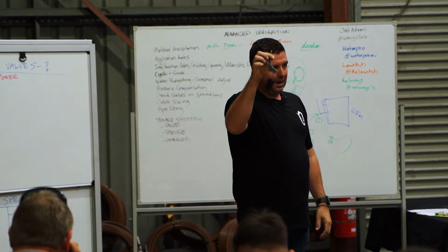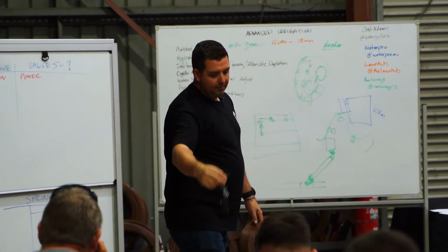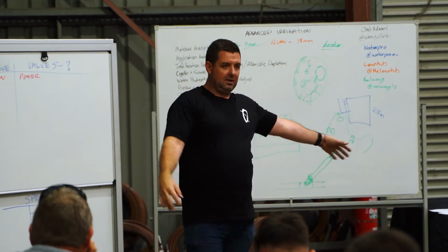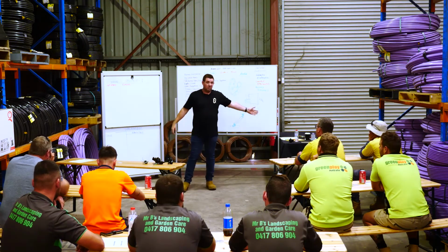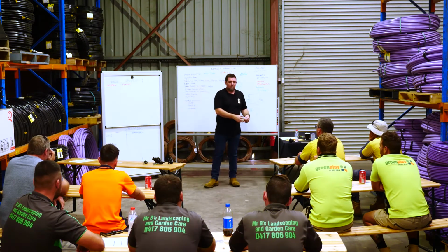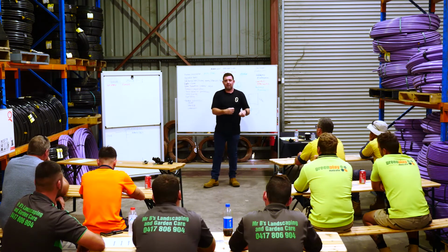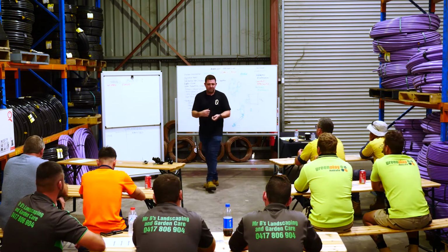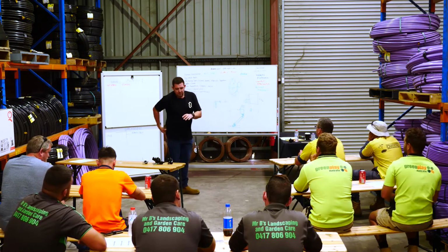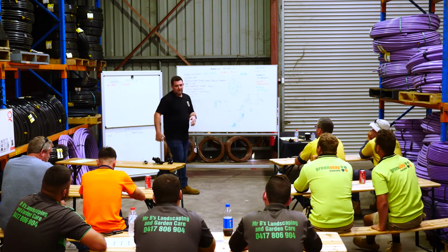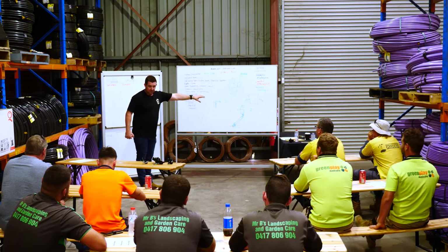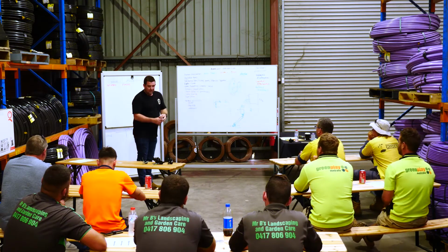If you're getting power at the controller through that, but you're not getting it out at the valve, there's a cable issue. You could run a new length of cable out to the valve. We're trying to avoid cutting those cables and start playing with that, because once we've cut the cables, we've got to get new wire joiners, or we've got to replace stuff. But the first case would be to check the controller. Second would be to check the wire joins at the other end. Third would be to check the actual coil itself.